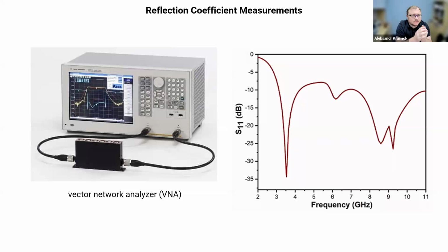For this reason, this VNA is a quite expensive device. The VNA I have in my lab can cost maybe 30, 50 thousand dollars. It's an expensive system exactly for this reason, because you need a very stable generator and a phase locking system to be able to measure phase.